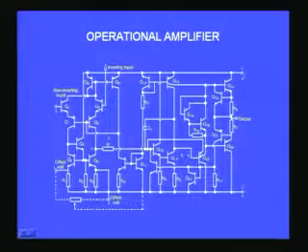Now let me move on to show you, not to frighten you, but to indicate to you the importance of the actual circuit inside the operational amplifier. I talked to you about the operational amplifier 741. This is a typical schematic diagram, circuit diagram of the 741 operational amplifier. There are some striking things that I wish you recognize immediately on seeing the picture. You have more transistors. The transistors are numbered here, Q1, Q2, Q3, Q4, etc. The last transistor is Q20. That means you have 20 transistors in this circuit.